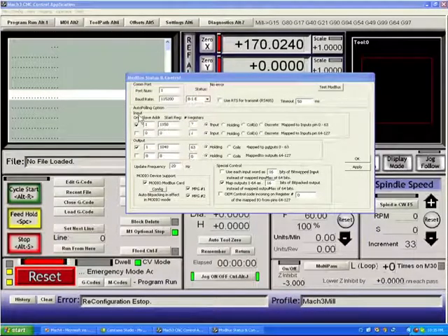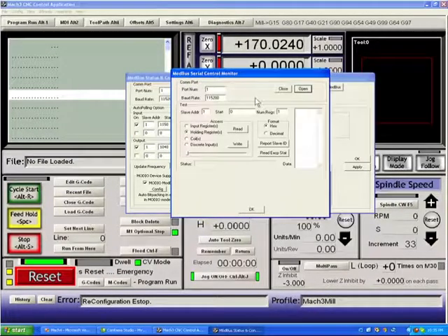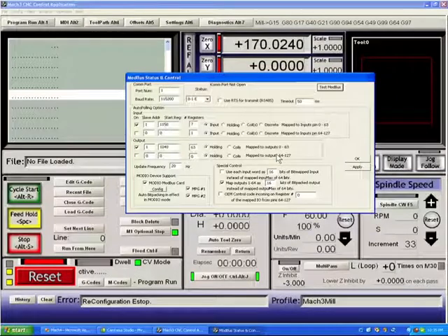So if you've just purchased a ModBus device and you're trying to set up a ModBus device, use your test ModBus control to test your memories to make sure that you do have communications, that you are getting the data that you wish. Generally speaking, the first 63 16-bit words that you transfer in to Mach3 become port 0, pins 0 to 63. A 1 in that 16-bit word will turn on that input, a 0 will turn it off.